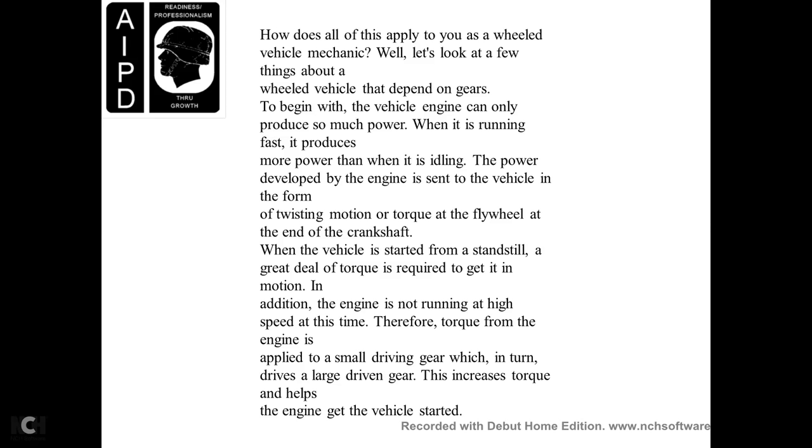How does this apply to the wheels of a vehicle? The mechanics look at the vehicle's gears. It depends on the gear that's driven by the vehicle engine. The engine can only produce so much power, but running fast it produces more power than when it is idling. The power developed by the engine is sent to the vehicle in the form of a twisting motion, torque, at the flywheel at the end of the crankshaft. To start the vehicle from a standstill, a lot of torque is required to get it into motion.